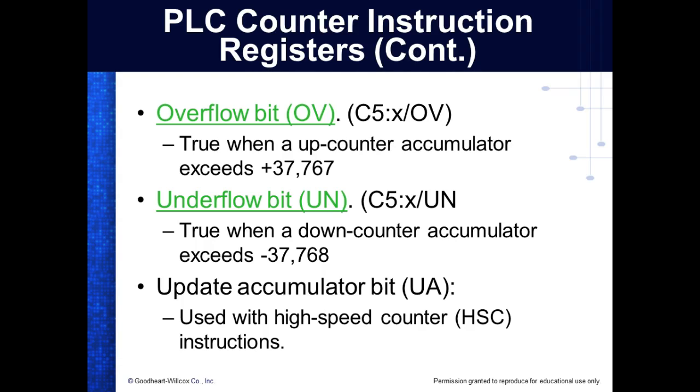As soon as I sacrifice one bit, I don't get 65,536 combinations anymore. I get 32,768, or 32,767 positive, because 0 takes up one of your positive spots, since zero is 16 zeros and has no weight. That's why with signed numbers we always have one more negative than positive.